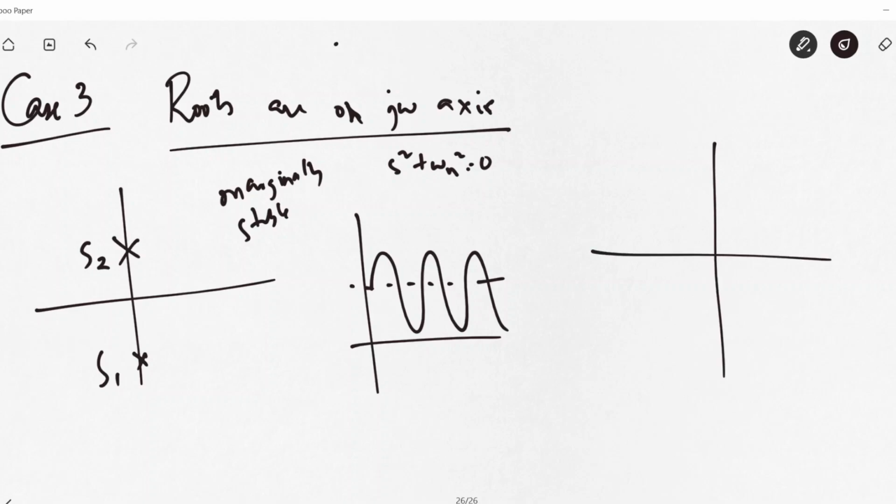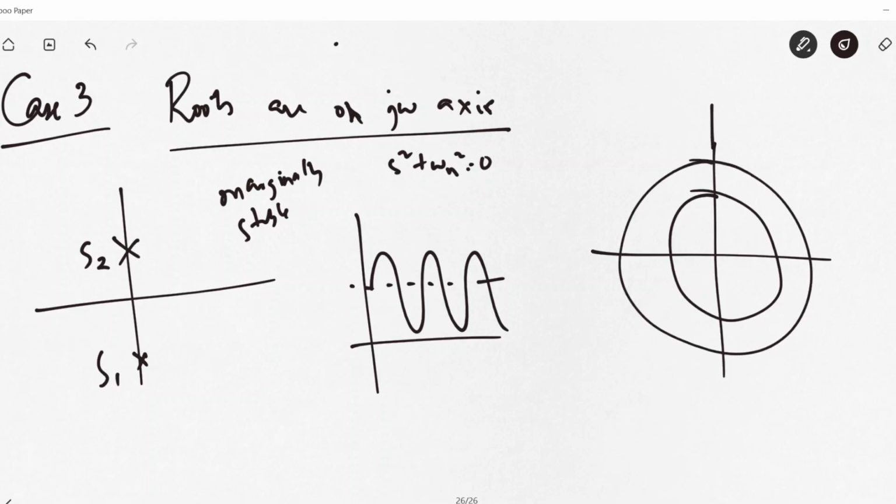And the phase portrait of such a system is actually what we have already plotted in an example that we did in the last session. Circular plots, circles. So a graph between x1 and x2 for such a system will be a circle, and the equilibrium point in such a case is known as a vortex. You can say it is a center point or a vortex. So we are obtaining closed paths in the phase plane.